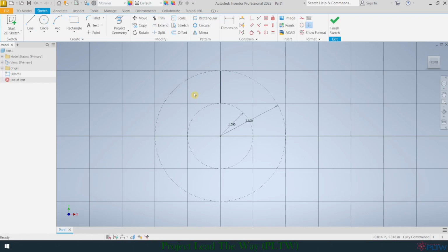Next, I'm going to draw several arcs, and the arcs may not make much sense, but it will actually create the actual shape of the Snail cam, and we'll have to make some adjustments using the dimension tool to get it correct. I'm going to go to arc, and this will be the 3-point arc. I'm going to start this first arc by clicking on the bottom of this line here, and then the end point of this arc, I'm going to make about 25% from this inner circle. So 25% from this circle to this circle is about where I want this one to end.